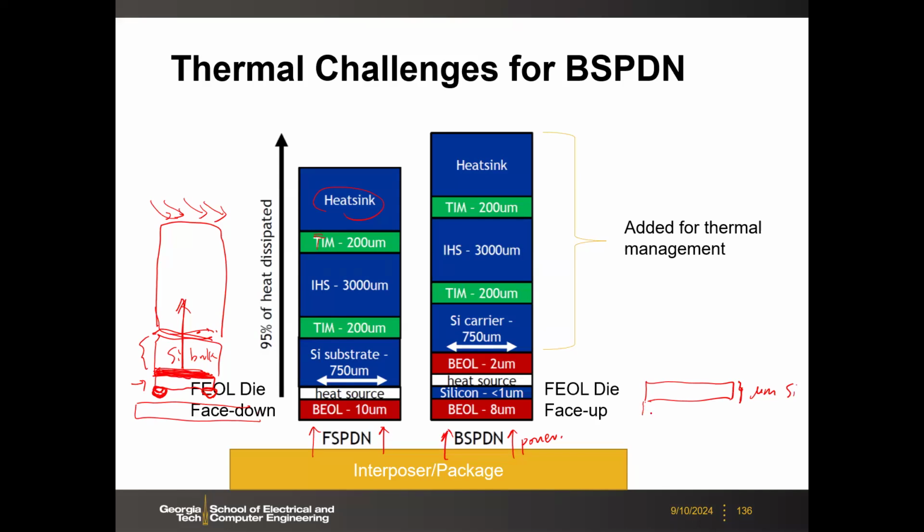And then you have your backside power delivery PDN here, and you have the power in. This will be your transistor, and then we have the nano TSV connecting this. And then you have the signal routing and the regular BEOL. So basically the die is facing up.